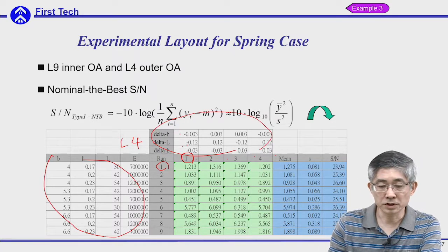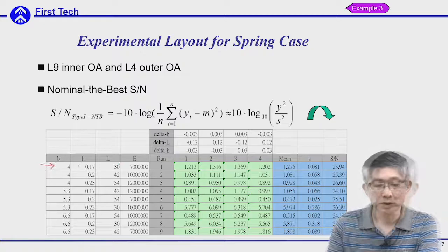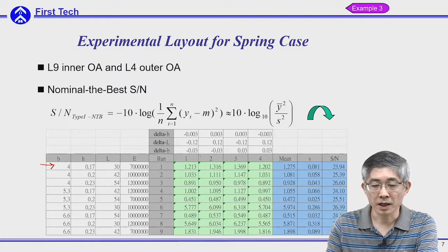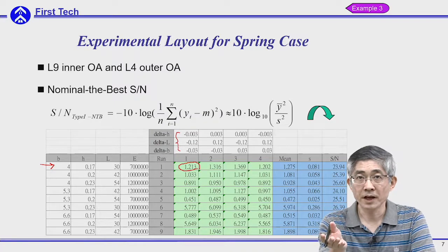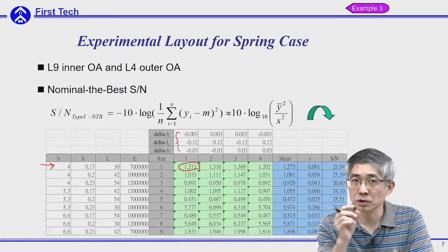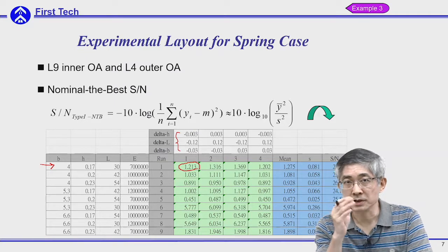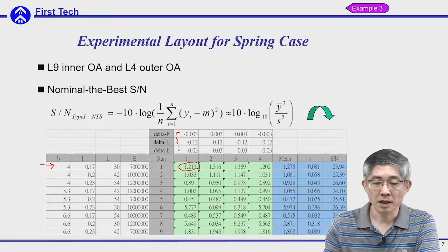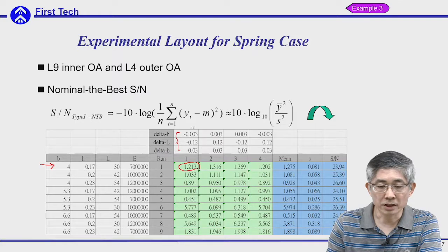So for the first treatment, which has the control factor design like this, at the first sample, we need to consider the influence of the noise factors. The actual values of each control factor will be slightly shifted due to the manufacturing errors. Then you can substitute the actual value.